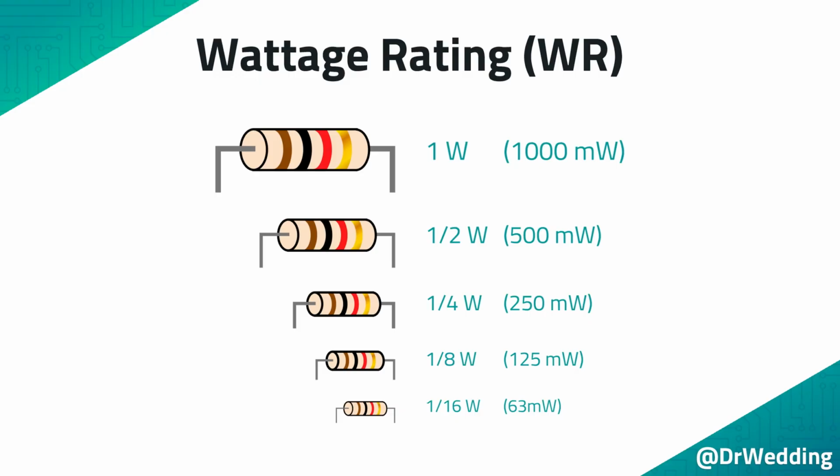Resistors under 1 watt are in standard increments. The resistors are cut in half with each step. A 1-watt resistor can withstand 1,000 milliwatts without damage. The next size down is a half-watt resistor that can withstand 500 milliwatts without damage. The next size down is a quarter-watt resistor, then an 1/8 watt, and then a 1/16 watt. There are smaller resistors, but they are not going to be discussed in this video series.